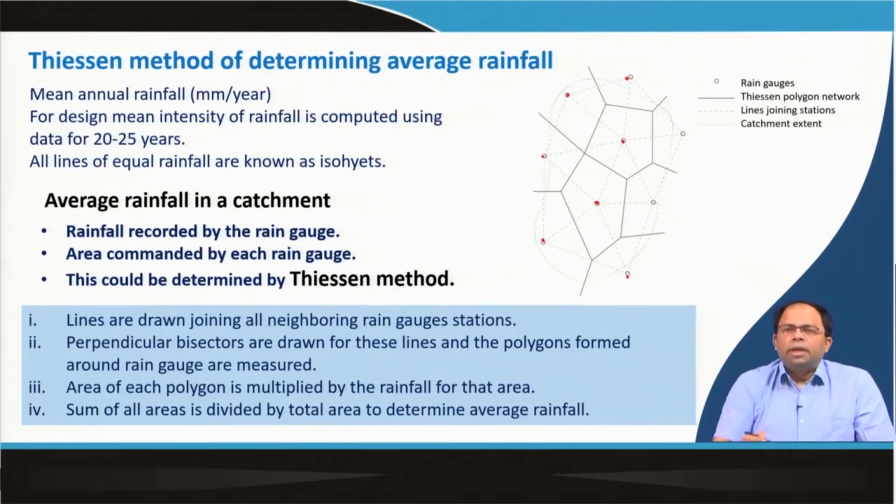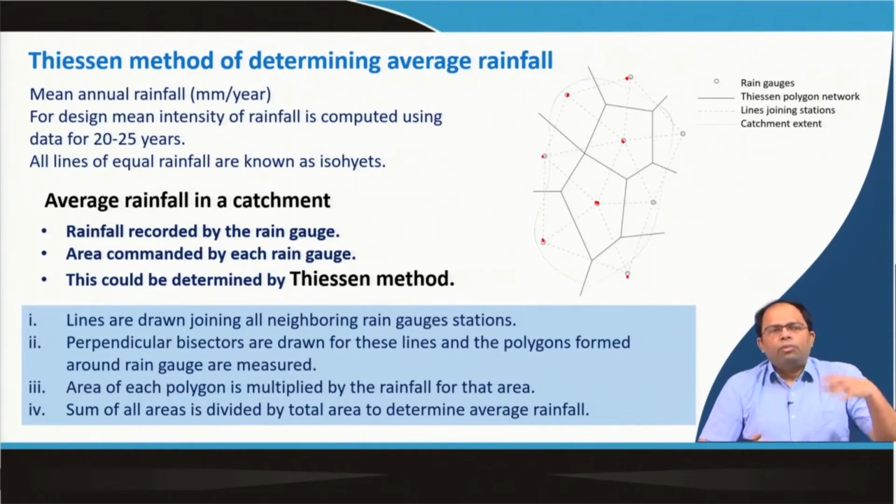In this area there could be several rain gauges, as we have fixed over here, but the point is, the rainfall is not uniform all throughout during a certain rainfall event. At different points we will find different amounts of rain. At one point in an area there is rainfall, and just beside that there is no rainfall, right? So, there are differences in both the intensity of rainfall as well as the occurrence of rainfall, which may happen in one area and not in another.